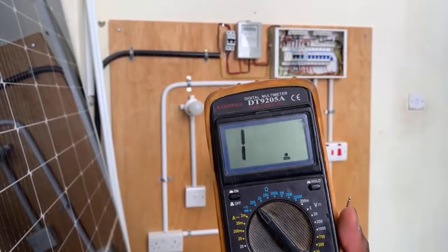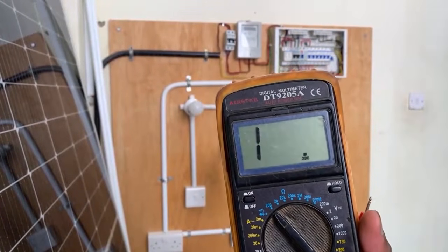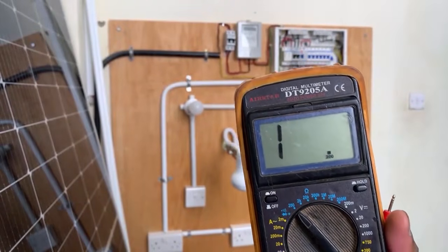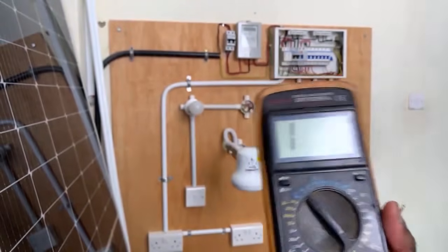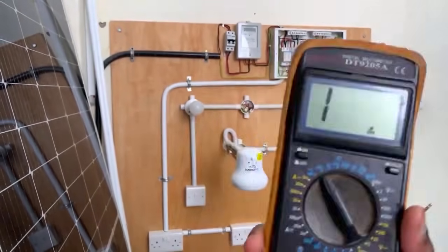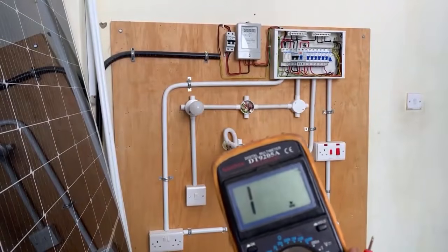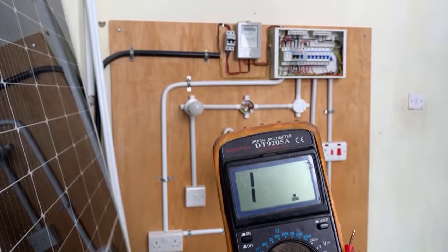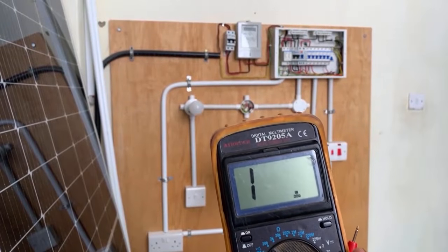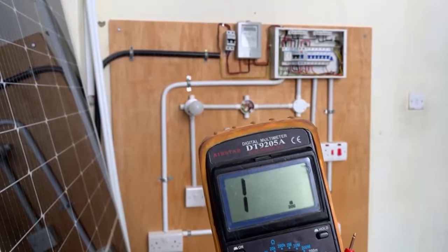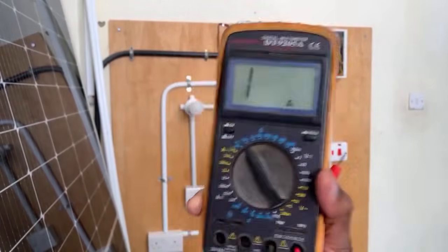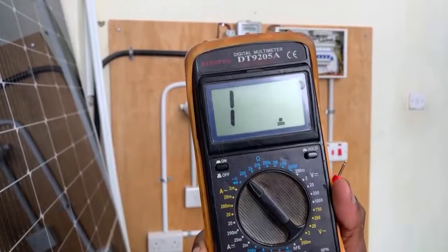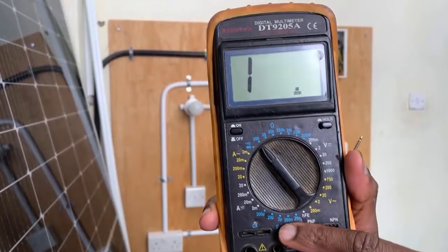You're recording direct current. And first of all, if you want to use a multimeter, you have to know that you will have to isolate that circuit. I hope we know that, because you have to place the digital multimeter in series with that circuit. So let's say you have power or current flowing through a bulb from a battery. So you will simply cut that wire or disconnect it and place your probes in series so that you can record the current.